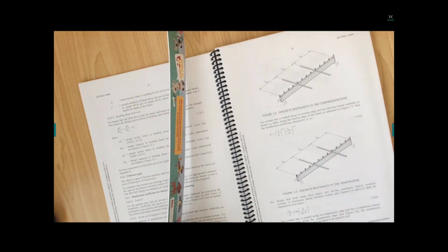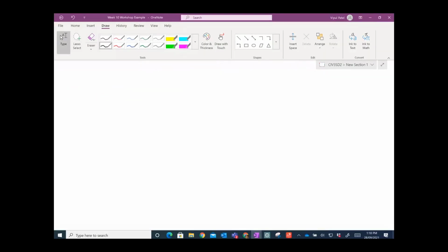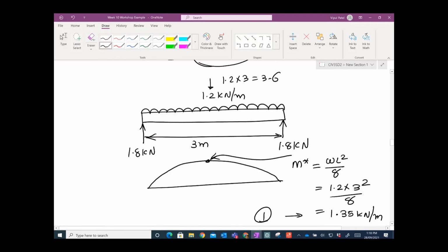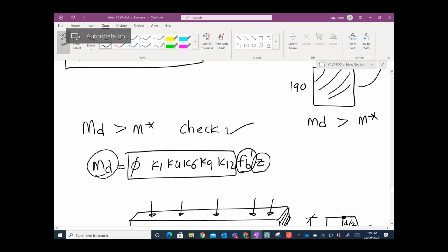In our examples, they say that your beam will not be restrained along the length of the stringers. It's just going to be restrained at the end. It's written here that both stringers are laterally restrained only at the bearer support. So it's only restrained here, and we calculate 3500 millimeters. You remember that we calculated 3500 millimeters here. So restraints only apply at 3500 millimeters, and LAY would be 3500.